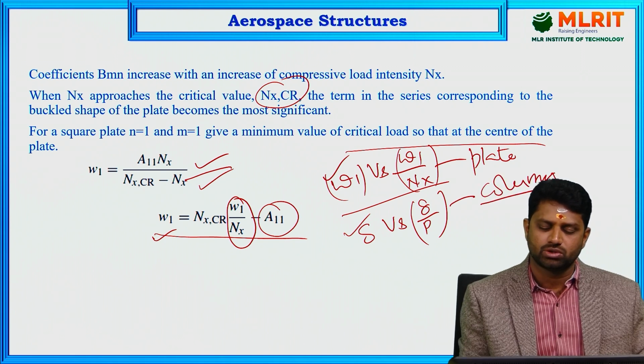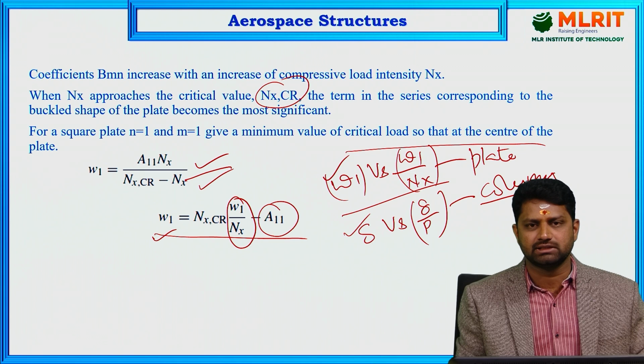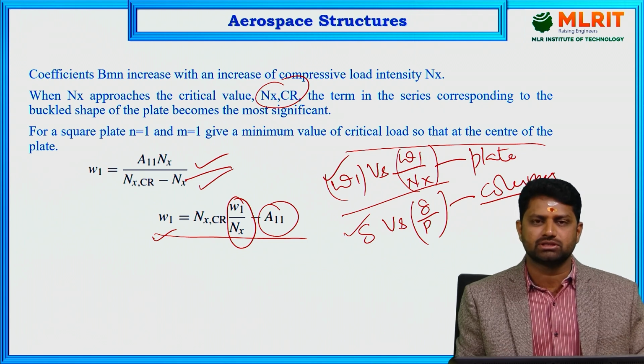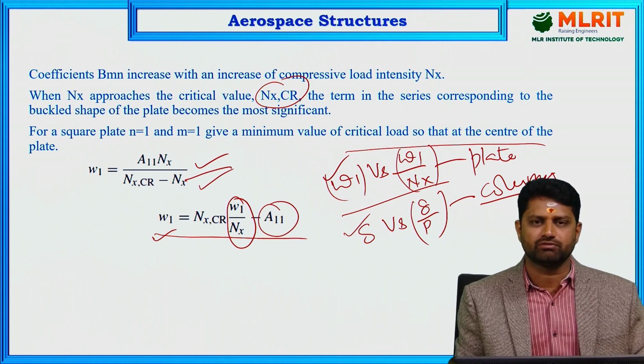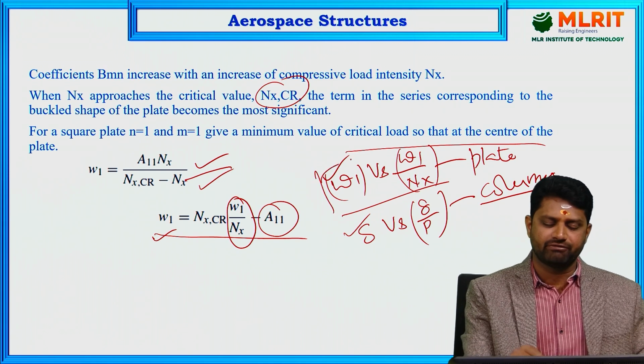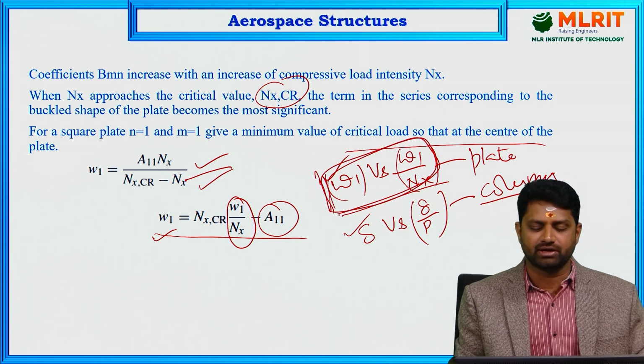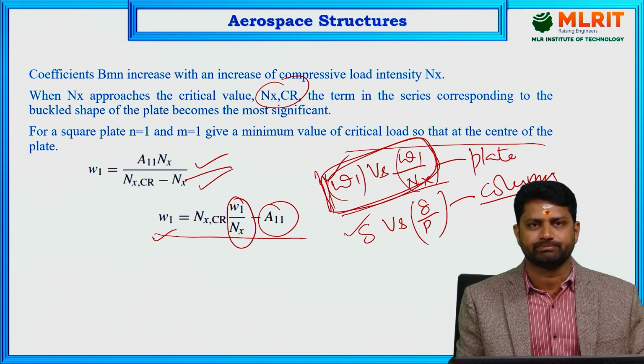Okay. So that is why we saw in the starting that the concept of buckling and critical load of a column will be extended to the thin plate. In a similar manner, by making use of the Southwell plot, we can determine it experimentally. When you plot this graph, you can clearly find the experimental determination of critical load from this plot.